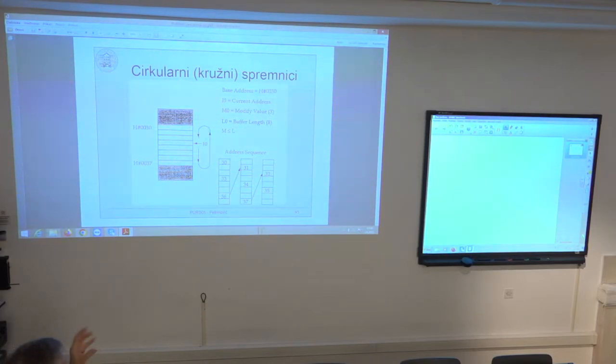To define this value, the size of the buffer, there is a special register. In this case, L0 directly corresponds to the I0 register. They cannot be mixed like the I and M registers; L3, for example, always corresponds to register I3.